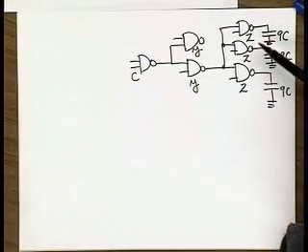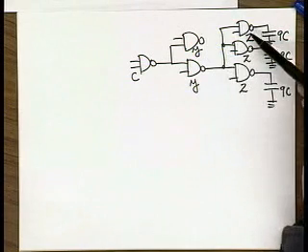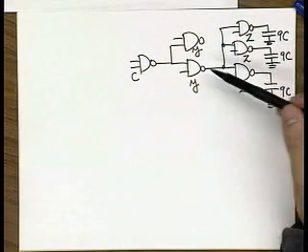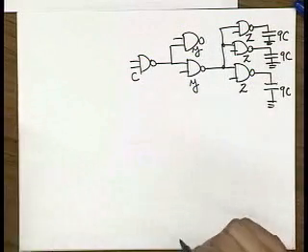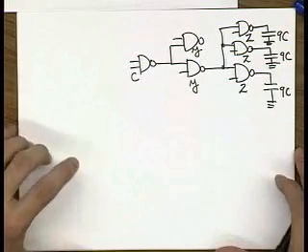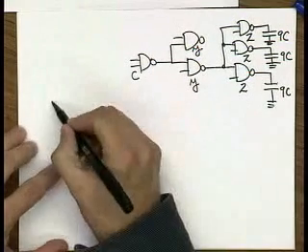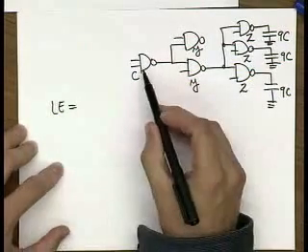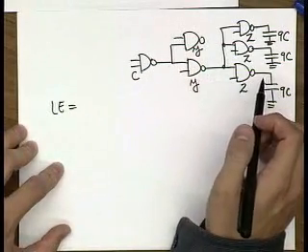So in this case, we have perfectly symmetric case because we have equal load, we have branching with the same type of gates, so y's and z's are the same. So now, in order to analyze this network, first thing we need to do, logical effort, right? So the total logical effort is a product of logical efforts of the stage 1, stage 2, and stage 3.